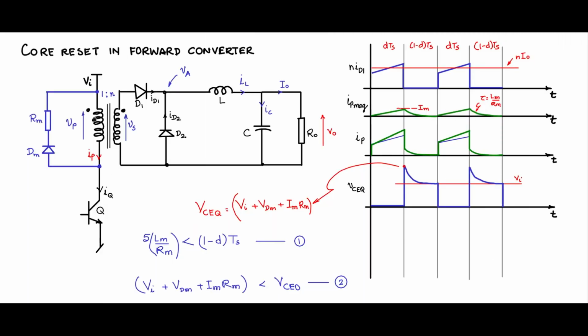There is one important variable that we will not be able to measure and see on the oscilloscope, and that is the flux inside this core. We have been talking of core resetting, the flux which is to be reset, but we will not be able to see the flux waveform. But indirectly we can know how it looks.